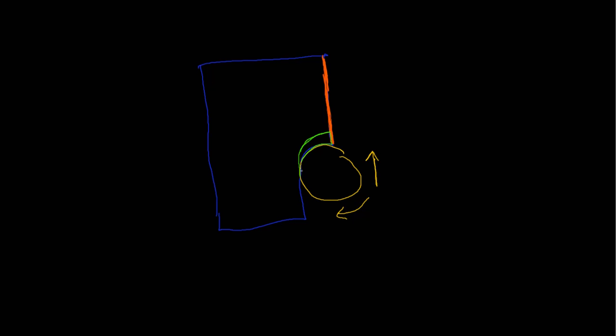And that causes less tool wear than cutting and taking a bite out of this scaled surface. So even though you're increasing the work hardening through the chip, it's less hard than this material, so that'll increase your tool life. So that's one reason why you would use conventional milling.